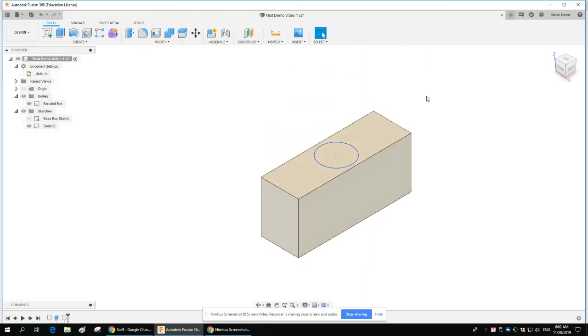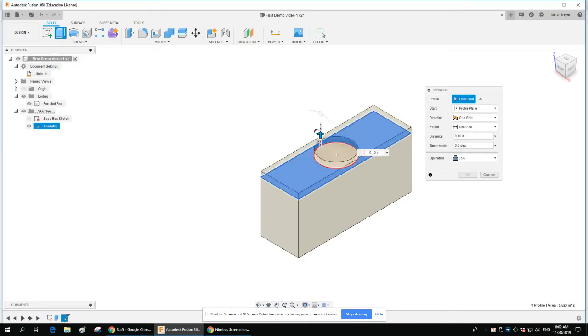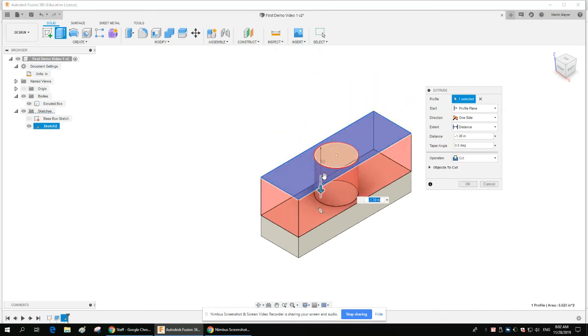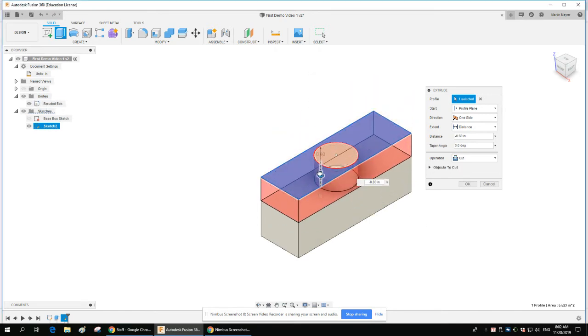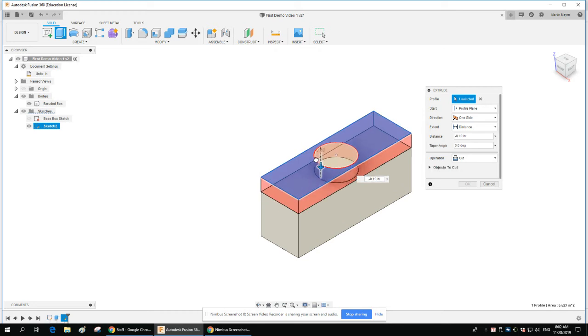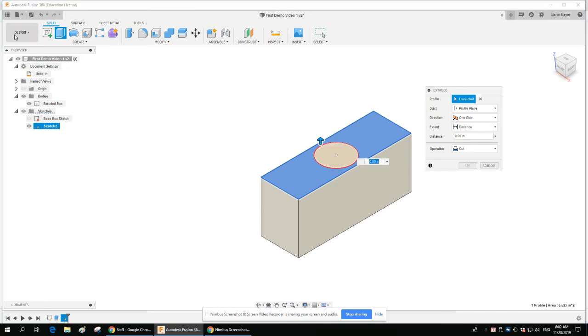I'm going to finish the sketch, and I'm going to go to extrude. It picks what do you want to extrude. I could extrude that if I wanted to. Notice when you're extruding, it's adding length to what was already extruded. If I go the other way, it's subtracting length from what was already there. So when I bring it back to an extrude of 0, I'm back to the original face, not some other length from a previous extrusion. So that's a little bit kind of weird to understand. I may not like that.